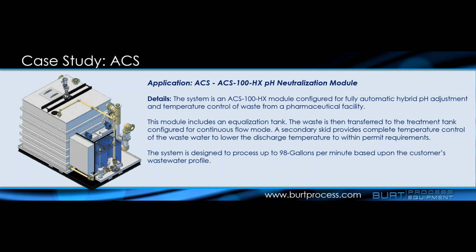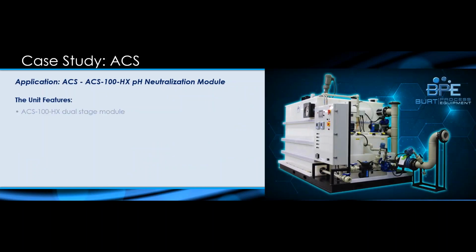Generally, the temperature control is on the influent side of your pH system, because you don't want to be designing your pH system for high temperatures. You really want to be designing it for corrosion resistance. So 3D models for these systems are also available online.